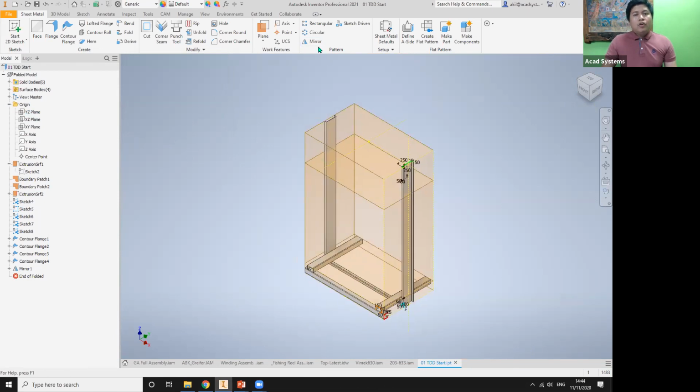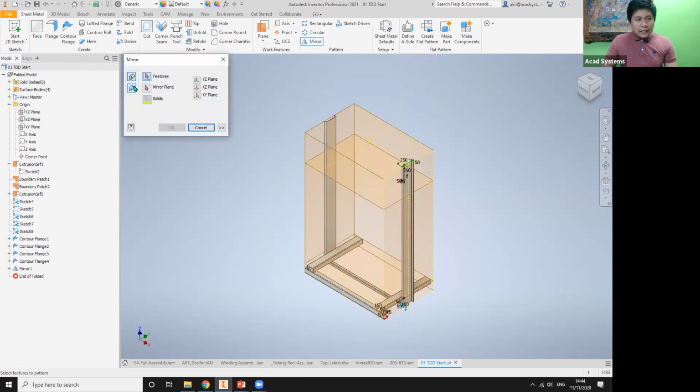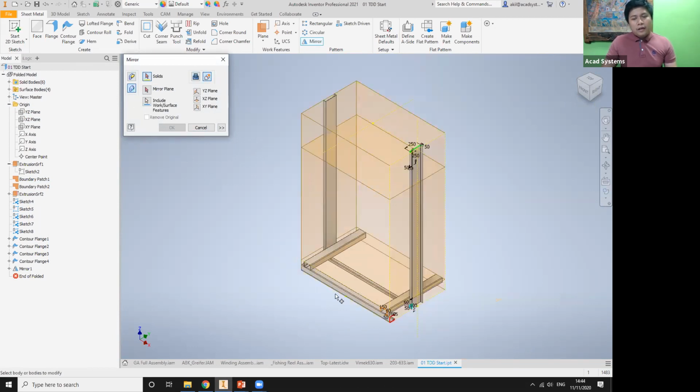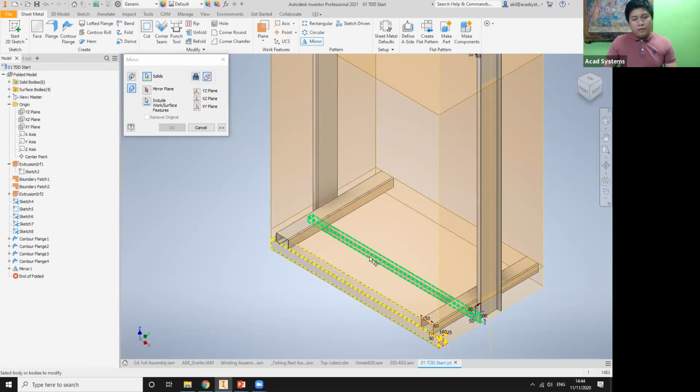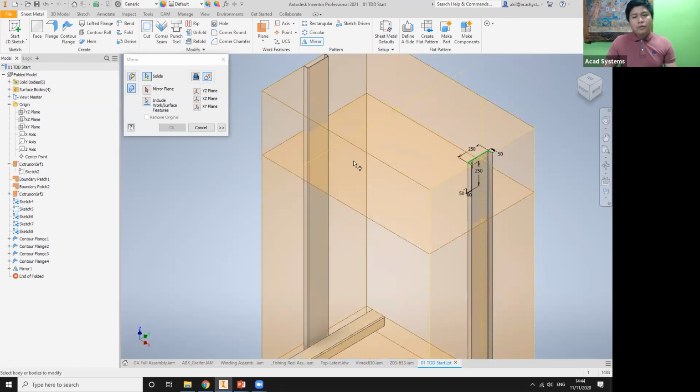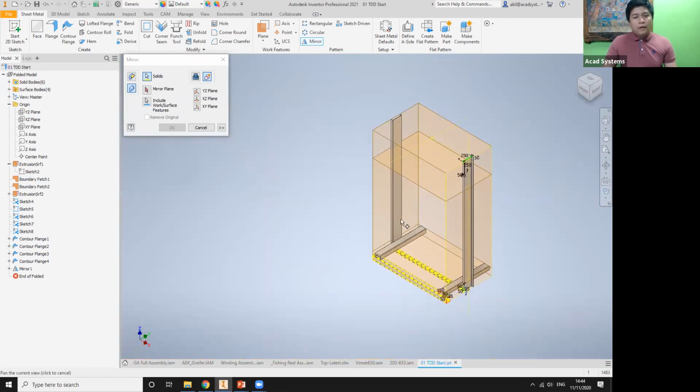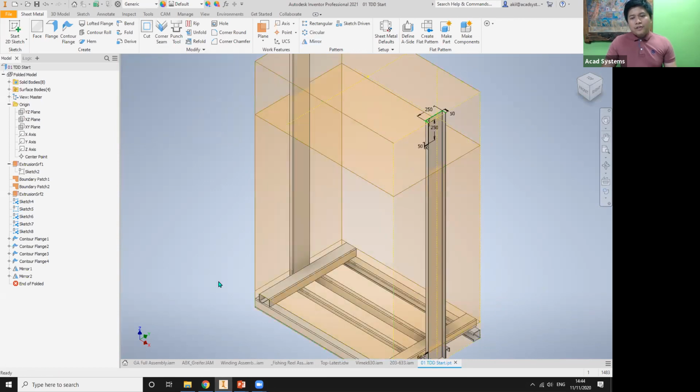All right. Mirror again. For this case, click on this mirror solid, new solid, select object. The objects I want to mirror are this one, 1, 2, and also this one, but it's okay. For the mirror plane, I go with XZ plane. It will change here.